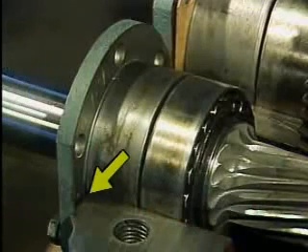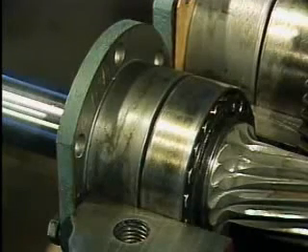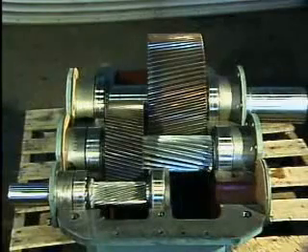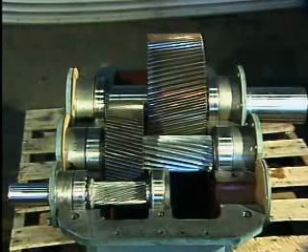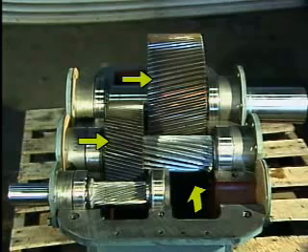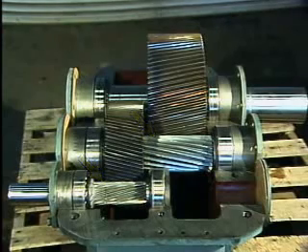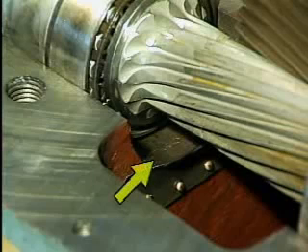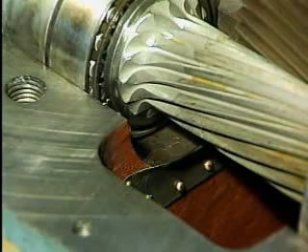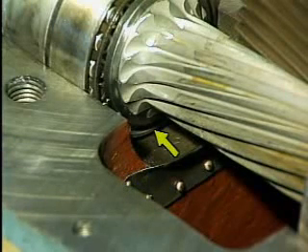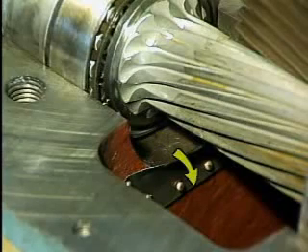Spacers, or shims, are placed between the bearing housings and the end caps to properly position the bearings, shafts, and gears inside the casing halves. This gearbox uses wet sump lubrication. This means that the larger gears would be partially submerged in the oil sump in the lower casing. As the gears rotate, they would pick up oil from the sump and transfer it to the pinions. Part of the oil which is slung off the gears and pinions would collect in troughs in the lower casing. These troughs direct the oil to the bearings, and any excess oil in these troughs would overflow back to the sump.